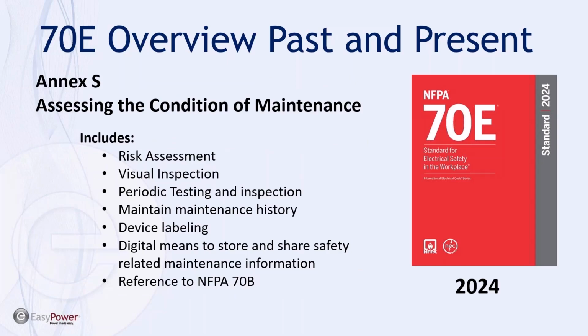So if a company asked me today to get started, where do we begin if we haven't done anything yet? And ultimately the checklist that we give them is you need to do a risk assessment, because OSHA ultimately is wanting you to assess the hazards of your workplace and of your facility. So ultimately the arc flash study begins that foundational building block of providing the information to do a risk assessment.